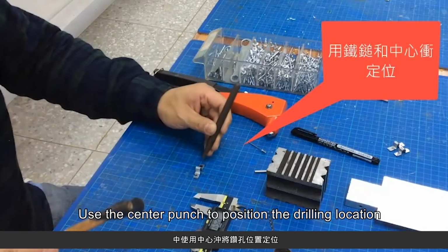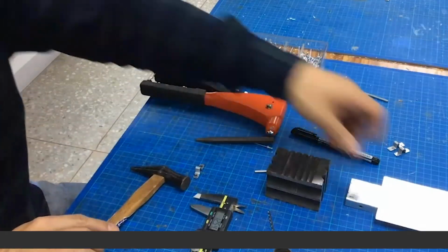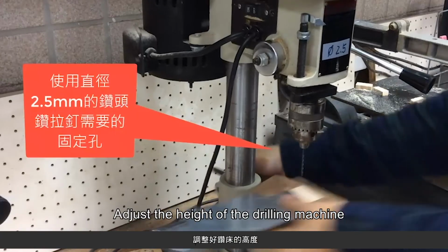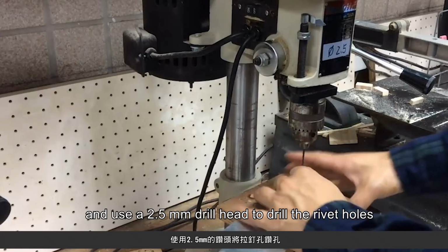Use the center punch to position the drilling location. Adjust the height of the drilling machine and use a 2.5mm drill head to drill the rivet holes.